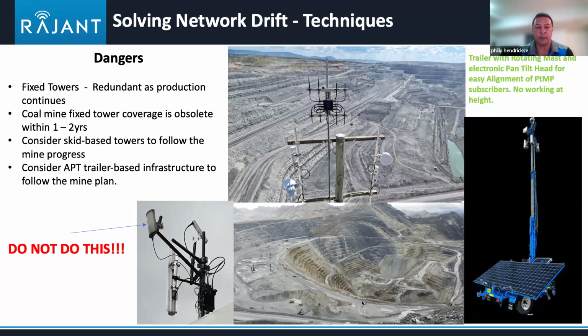You might be 500 to 600 meters high with an infrastructure trailer, and the first thing you don't do is go and buy 10 sector antennas and then just try and point them down into the pit. You have to remember that the elevation beam width is on the truck antenna itself. It cannot see up 45 degrees. Well, it can't see much further than 15 degrees.